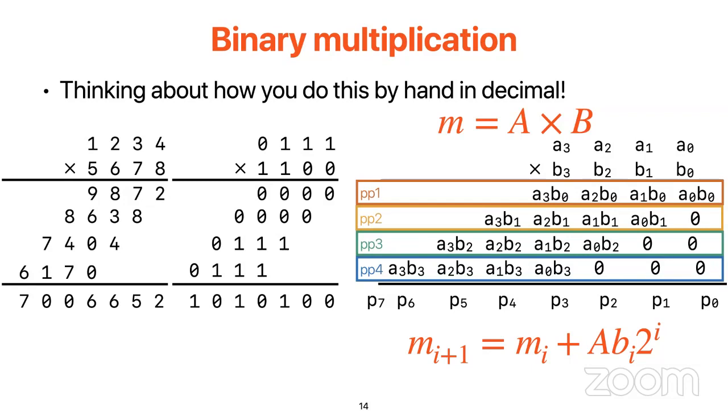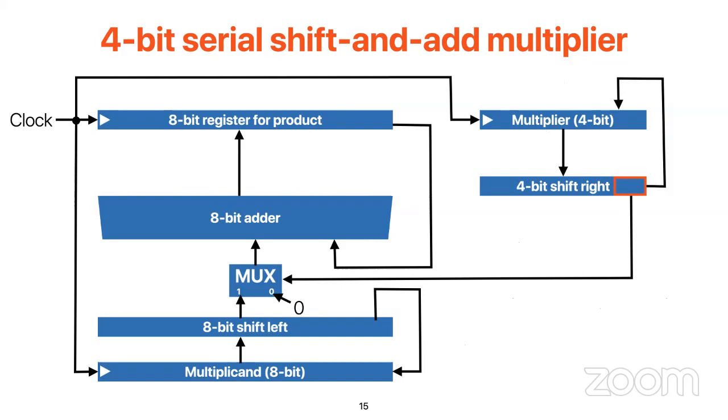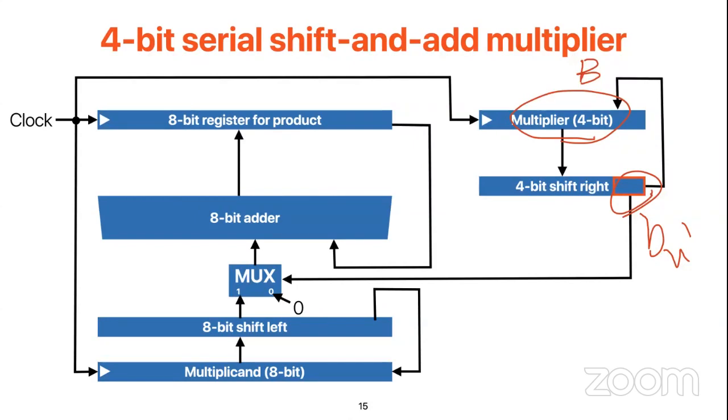So if we want to design a circuit like this, the basic idea is probably we are going to produce a sequential circuit like this. First of all, the input for every cycle is basically your multiplier, and because this is the B, we only need the Bi at each moment. After you use the Bi, you never want to reuse it. So let's shift it right, and take the last bit as the input. And because it's a binary number, you can only have 0 or 1, right?